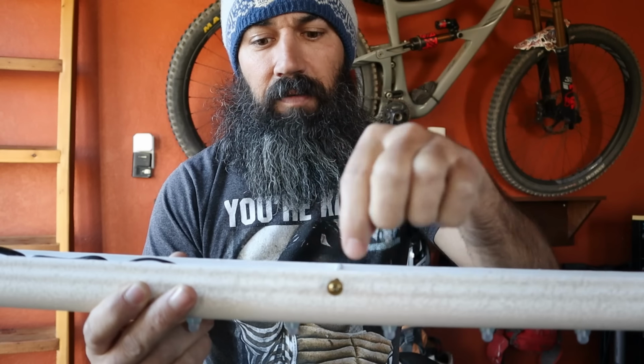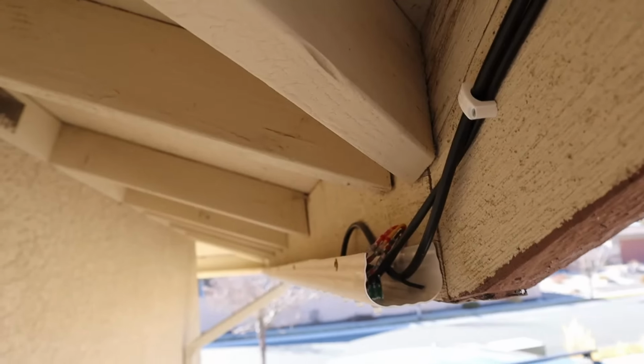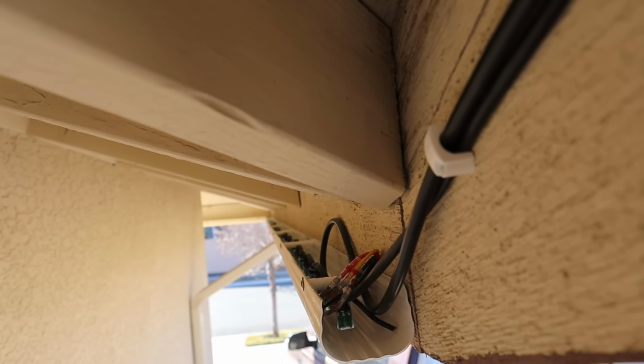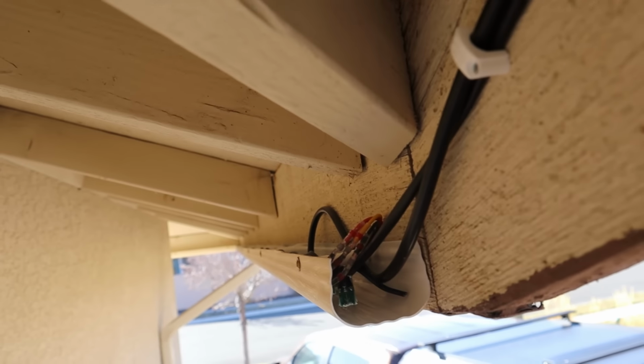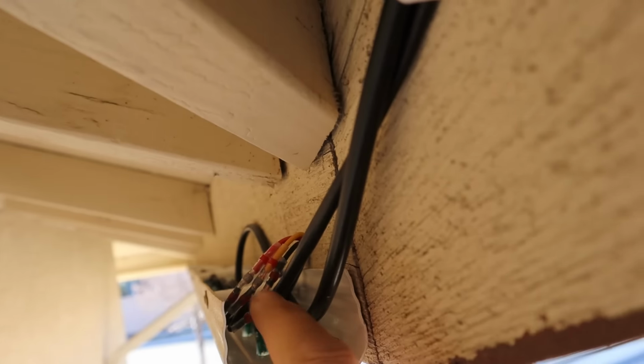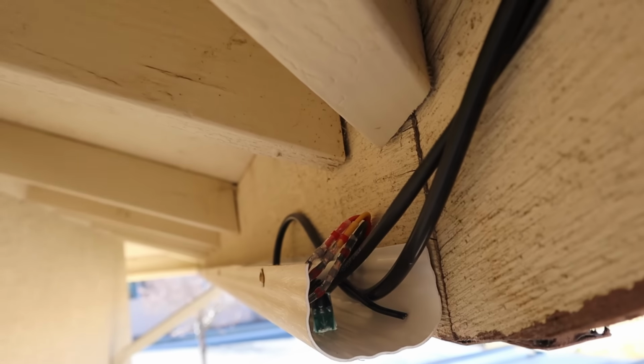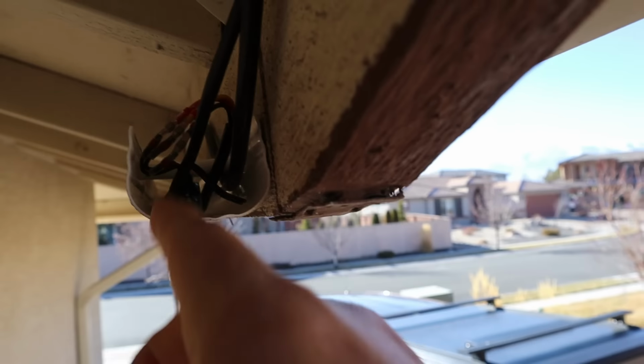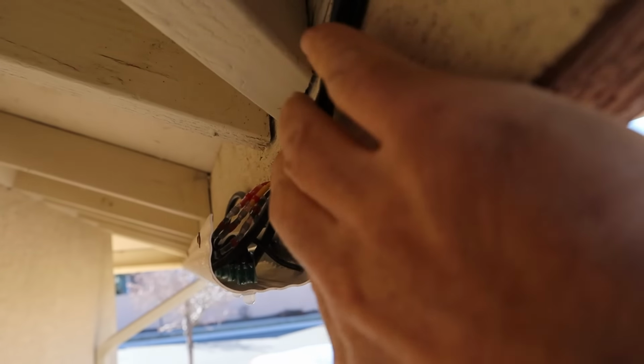So they're always in between so that it didn't interfere with the pixels themselves. So here's what it looks like mounted on the back of the fascia itself. You can see I just get the bottom of the channel about even with the fascia, and then you can see those spacers and screws going across, and then the pixel strands, and then there's my power injection wire, which I'll get to in just a little bit.